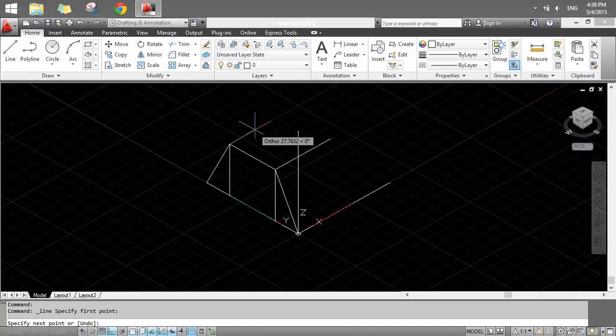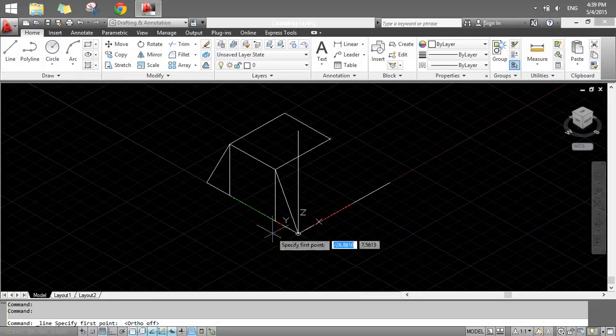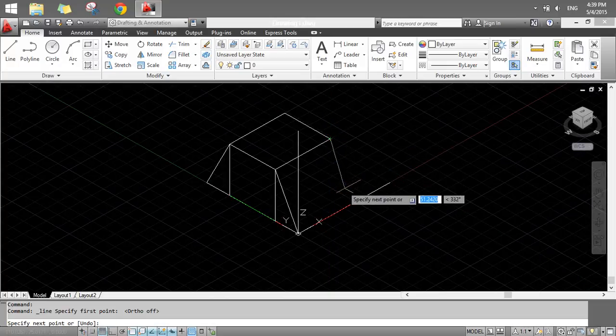degree. Make sure the angle is set, and sometimes when you're dragging the unit bar will not show up, so just press backspace on your keyboard and this menu bar will open up. Just press backspace again, type 60, here you go. Press the line button again, join these 2 points. Line again. Now before drawing vertical lines, make sure ortho mode is on, line, drag it to the end of this red line.